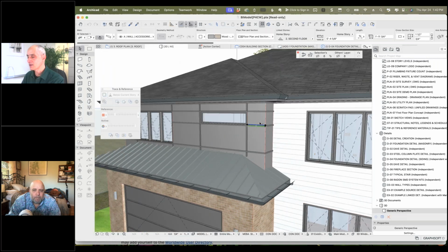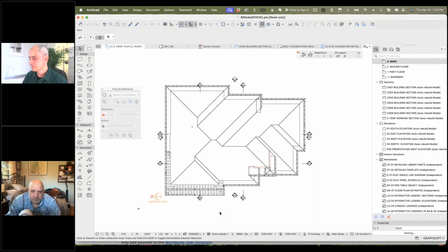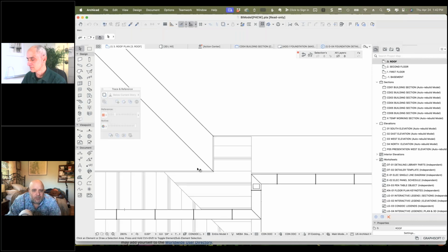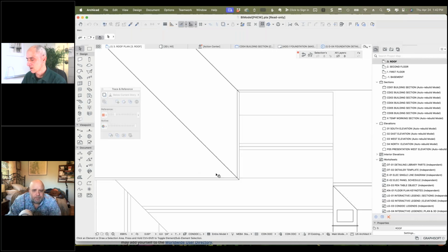And if we look at the modeling stuff, did you do these just manually, just placing them in an elevation and then moving them on plan to the right location? Yeah, I placed them in plan view first, and then from either 3D or elevation view, copy or drag a copy, reposition, adjust the dimensions.